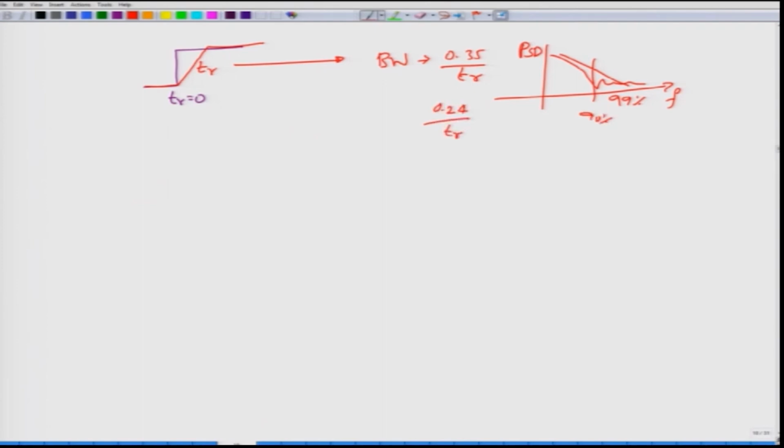Most importantly, if there is a fault, so there is some discontinuity on the transmission line, and the location happens to be such that the time delay for the pulse to reach there and come back would be less than this TR, then even as the pulse is changing slowly with a slow TR, the reflection would have come and then it would cause the total voltage to go something like this. I have not derived all this, but you can actually do that by looking at the references which I would suggest during the course.